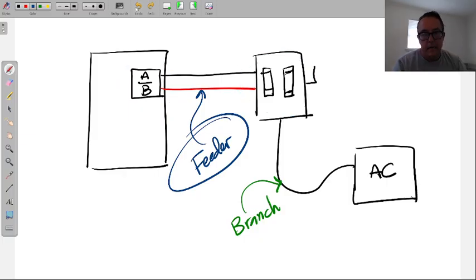Could you repeat that? Yep. Let's go back even one more. If the wires, the conductors, however you want to write that down, I'm going to put wires just to shorten that up. If the wires start at an overcurrent protection device and end at an overcurrent protection device, OCPD, right? Yes, OCPD, very good. Those are feeder wires. Starts at an OCPD, ends at an OCPD, feeders.